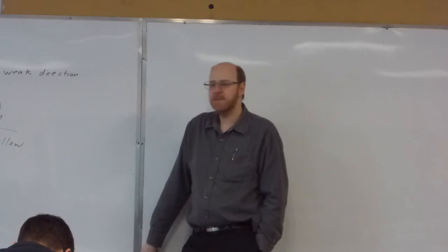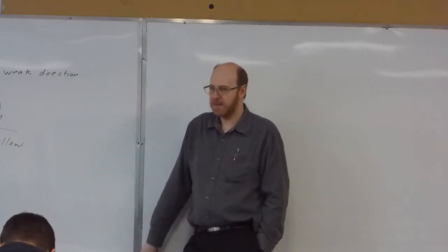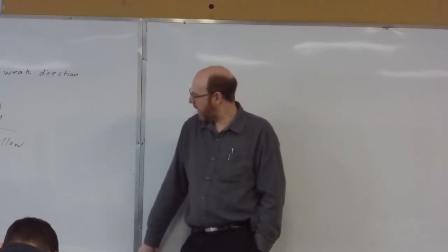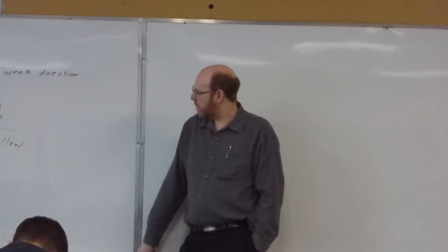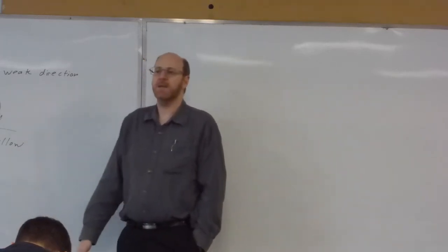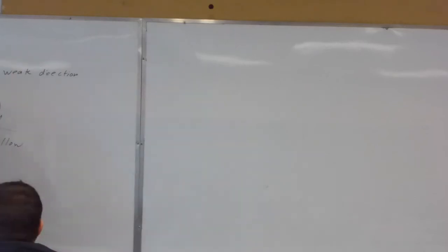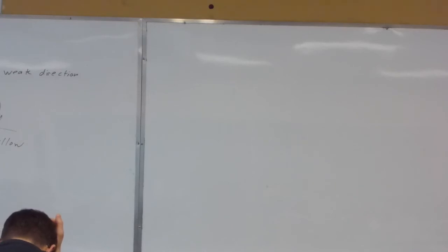Now, if you take a look at your welds, the phi factor is reduced yet again, so we're looking at 0.67. This is to account for a higher variability in welds. We looked at with a fillet weld, perpendicular versus parallel, and a slight little modification factor on the formula. And then there is actually a part of the formula that deals with both perpendicular and parallel at the same time. We tend to neglect that as much as possible. It just adds an extra term in the equation, but in most cases it doesn't really give us anything significant. Now the last thing that we looked at on steel was our composite decks.